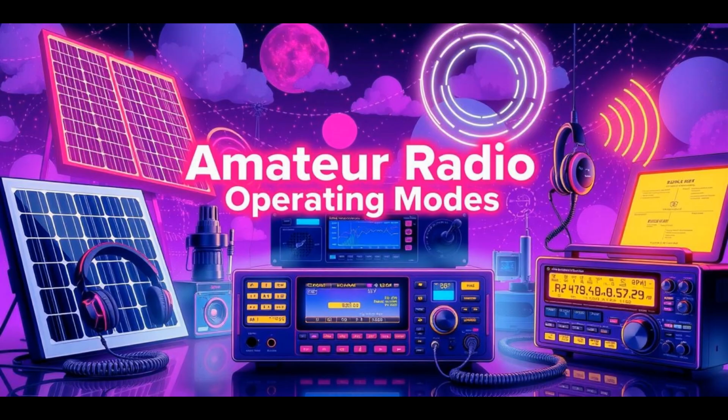In amateur radio, the term mode of operation, often shortened to just mode, refers to how the radio signal is transmitted, received, and interpreted. Essentially, mode is the method or format of communication being used between amateur radio operators. A mode of operation describes the technical method of modulation and signal processing a radio operator uses to send and receive information. It determines what the transmitted signal looks like and how the receiver must decode it.